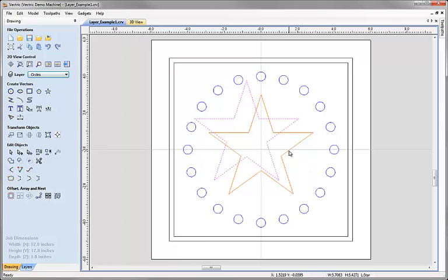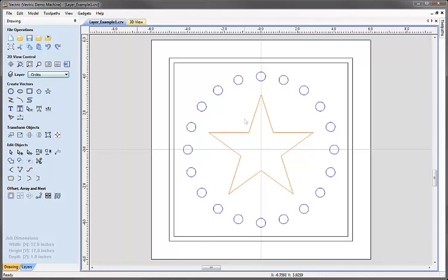When we use the copy option by holding the Control key down when we transform it, that will keep the vector on the layer of the original object that I copied. Let's just delete that extra star now. And although the logic differs between those two methods, you can see that the idea of right mouse clicking, copying something and pasting a new object is conceptually a little different than just clicking and dragging it, and that's why that behaviour is different. So we've seen a selection of methods for creating new layers, and it is also possible